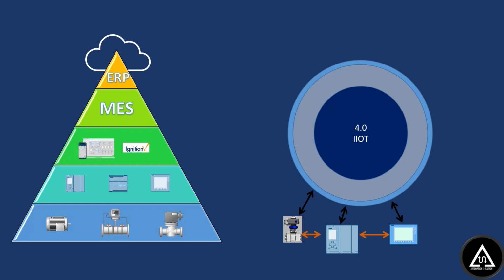So not only the field devices or the control devices, but even the SCADA will be connected to here. What is the benefit? What is the difference? The difference is in Industry 3.0, you will create tags for each of your motor sensors, and you will do those tags again to connect them to the SCADA system. In Industry 4.0, once you did the tags in the PLC, it will automatically appear in the SCADA.